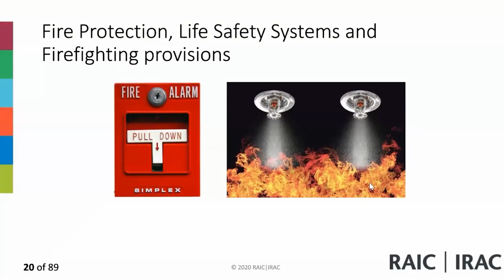That's one good exercise. As you see in the definitions, there are definitions within definitions. There are italic terms. So as you look for a definition, sometimes you're not sure what it means. You still have to dig down. For example, for interconnected floor space, there's a definition of floor area, and there's fire separation, and then you go find the definitions of these. It's a little bit complex, but once you know how to use it, it becomes easy.